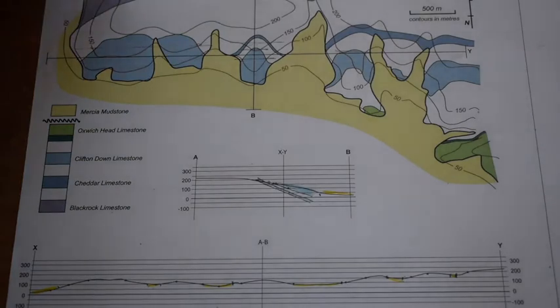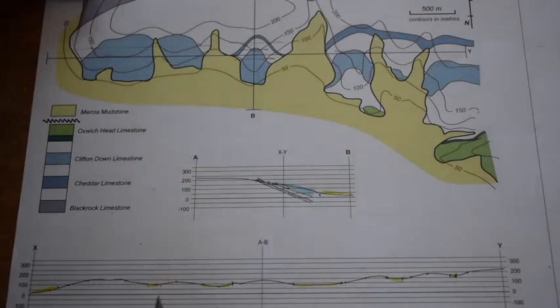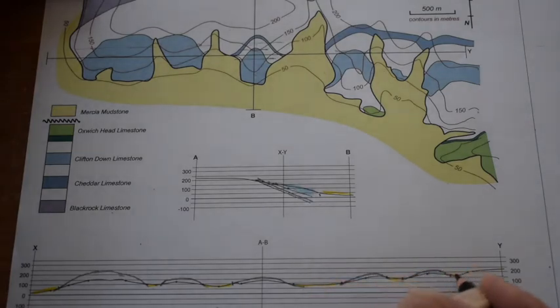So now we need to join these up by creating a surface that continues in the air and in the subsurface. Well, the Mercian mudstone's on top, so therefore the Mercian mudstone outcrop must continue and have been eroded over the top of this ground. I'm exaggerating it a bit, perhaps not quite as high as that, and then come down to there and then cut out again and down and out again and down, out again and down, out again and out again, so that the Mercian mudstone lies in low ground.